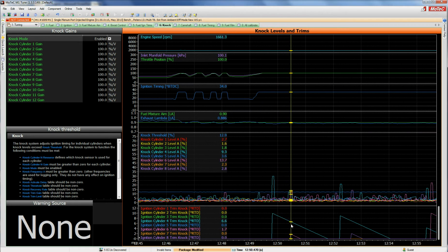The timing starts coming back in, and you can see that cylinder has another go at 7 with the 7 degrees out of it, and there is about 10 or 12 degrees too much timing in that for me to get it to rattle. Comes back down, not long, back at its normal setting, which of course was 32 degrees I think we had in it instead of about 22, and then bang, pings on that cylinder. It's obviously the hottest cylinder, cylinder number 4, and again it goes out. Only this time it only went, where are we, our threshold's 12, went 11 over. Alright, so 11 over, calculating around that 9 degree mark.